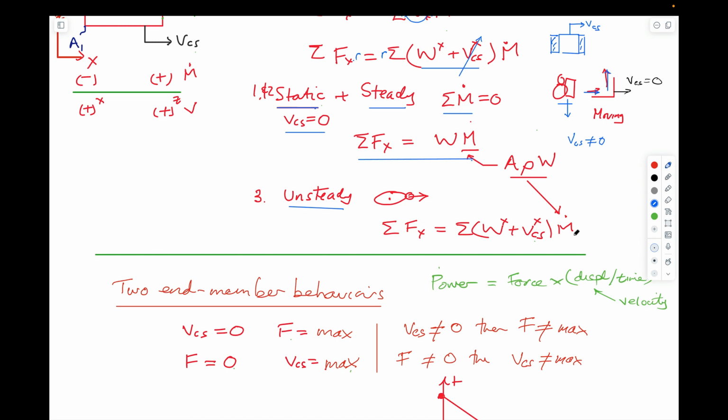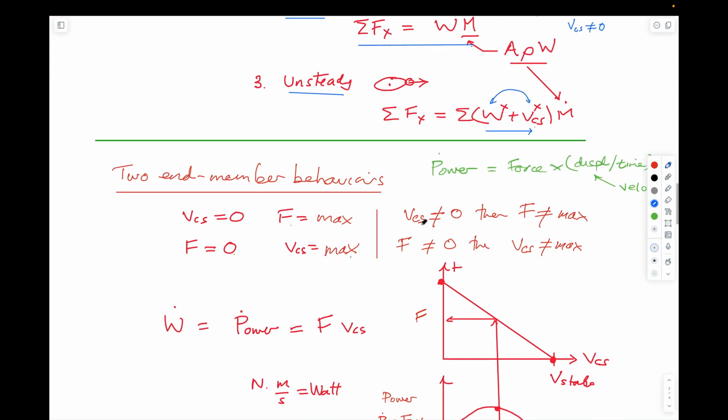The magnitude of this is equal to the area times density times the velocity that's coming out of the system. But we have to be able to accommodate the magnitude of these two. And again, as before, the only time that this can equal 0 when it's released is if these two components exactly balance each other. So we have a control system that is traveling at the effluent velocity of the fluid that's coming out of this decapitated cylinder.